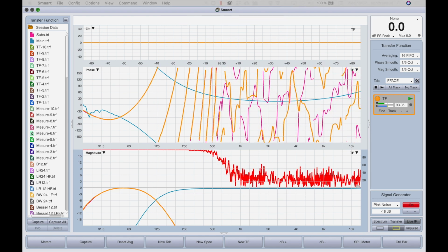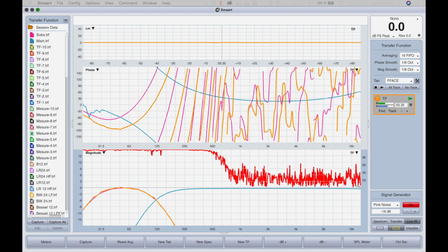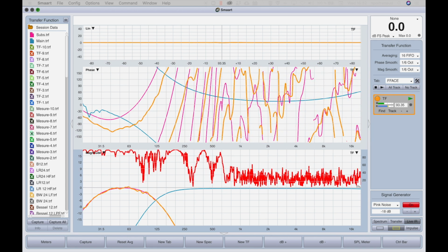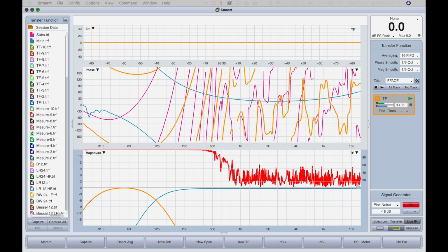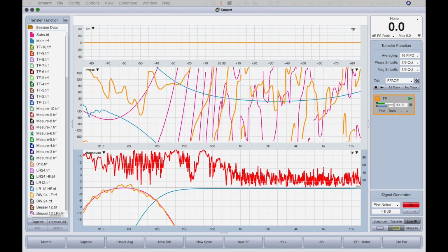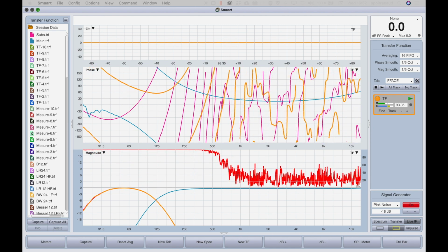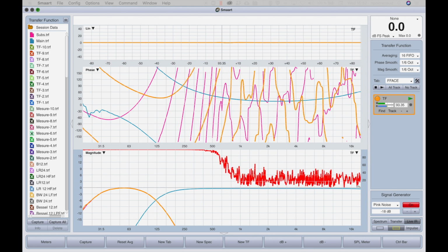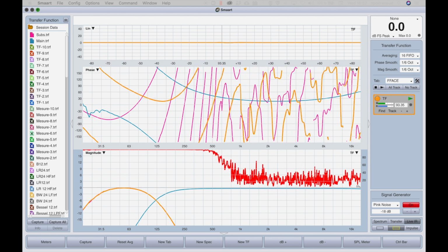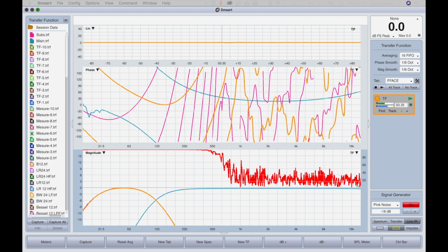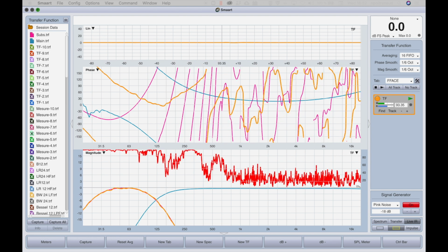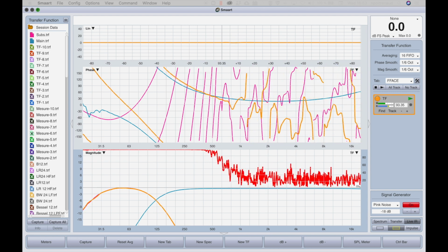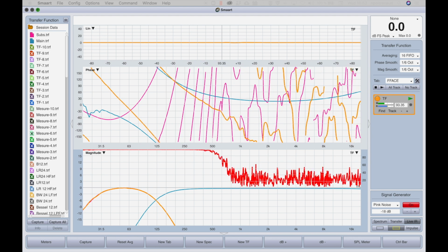to be as similar as possible to the blue trace at the crossover points. I know the value, but let's go 3. You see 3 is starting to move the frequency response. Let's go 8 now. And 8, okay, it's starting to be better. Again, increase manually. So this is 10. And I can again try to increase the value so that the phase trace is as similar as possible to the blue one. Currently this is 12 milliseconds. I can go maybe 15. So this is now 15. 15 is quite better, but maybe I should increase a little bit so that I can get a good matching at the crossover points.